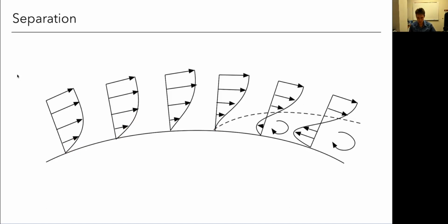So I actually have no forward momentum in the x direction. And by definition, that's separation, right? Because I'm no longer moving along the body. The only component of velocity I would have in this case is a small upward component. So the fluid is going to leave the body and recirculate around, filling that void, and I'm going to have this wake.